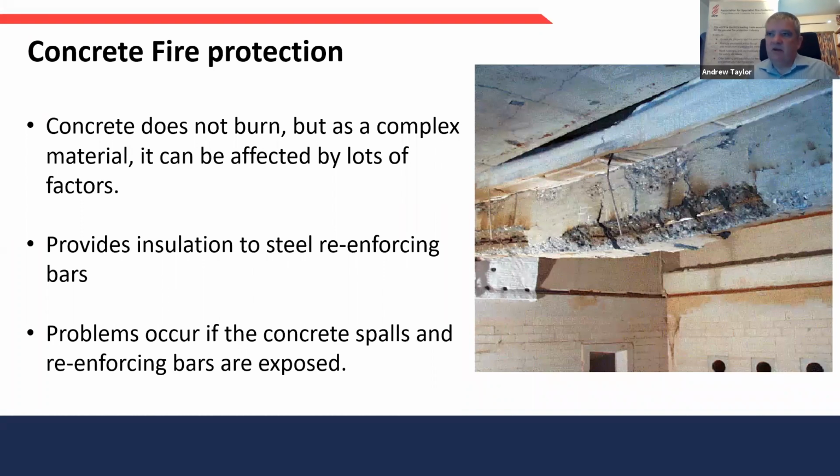Concrete, like steel, doesn't burn, but it's a complex material and there are lots of different factors within the makeup of the concrete that can affect its fire resistance performance. Basically, what the concrete is doing in bending mode like this is providing insulation to steel reinforcing bars. And one of the problems occurs if the concrete spalls and the reinforcing bars become exposed.